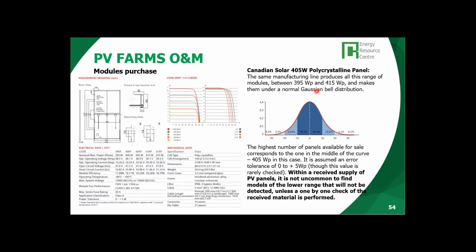So if you are planning a small system, the effect of these little differences between the generation curves, remember when we discussed the operational fashion of the PV panels, is small. But when we connect together modules that are a little bit below the rated capacity and add tens or hundreds of modules, that can translate into a serious reduction of the expected production of a PV farm.